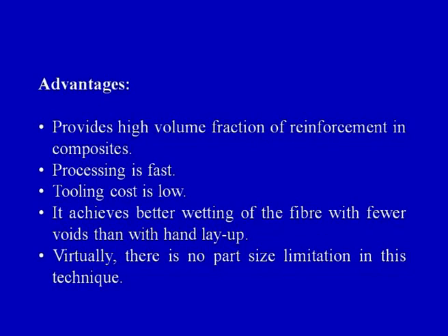So again I am going to revise the advantages of the spray layup process. It provides a high volume fraction of fiber or the reinforcement in the composite, the processing is fast and the tooling cost is low, and better wetting of the fibers takes place, which means that the strength of the resultant composite would be very high, and there is no part size limitation. This can be used for very big components or very big composite products.